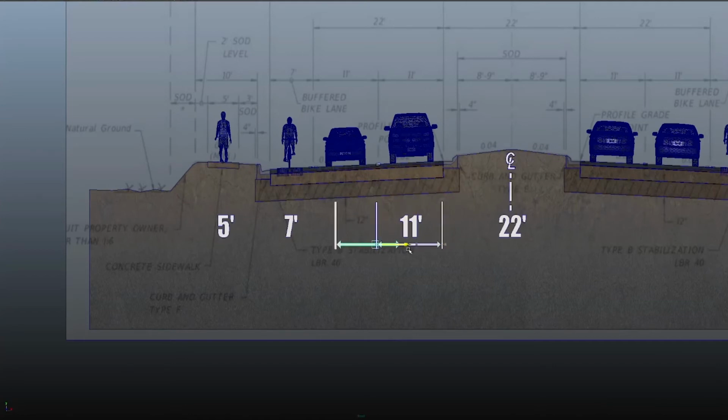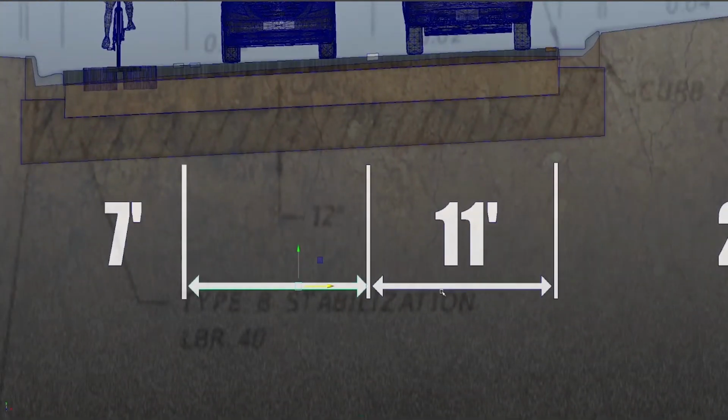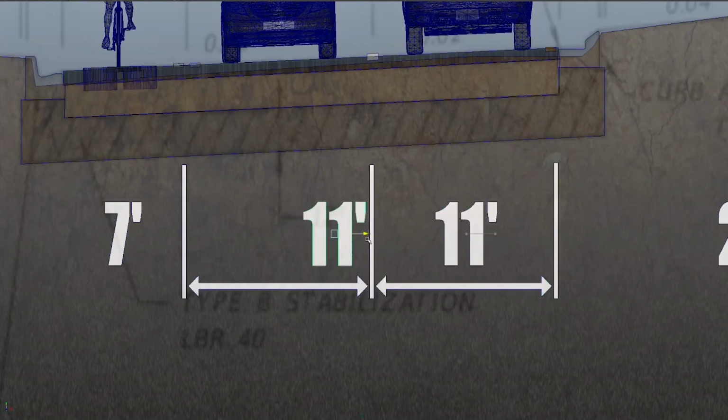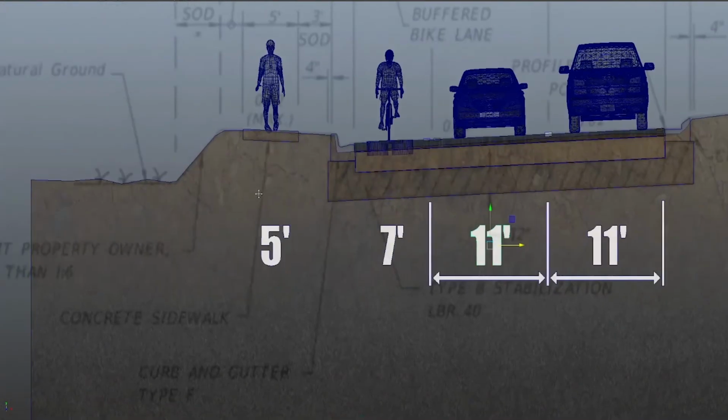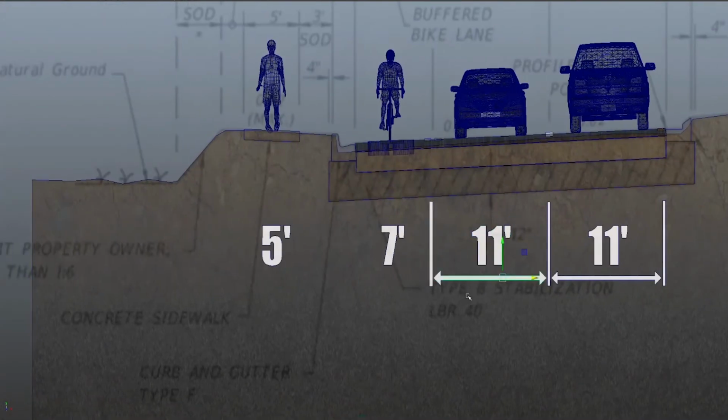Duplicate, and we don't want to recreate the wheel every time, so let's duplicate this. And you can see it's not quite lined up because I was kind of zoomed out a little bit. That's why we have the option to always tweak these things very quickly and very easily because they're just polys. Here we go, duplicate 11. So I'm just selecting these two objects, sliding them over, pushing and pulling the points to meet.